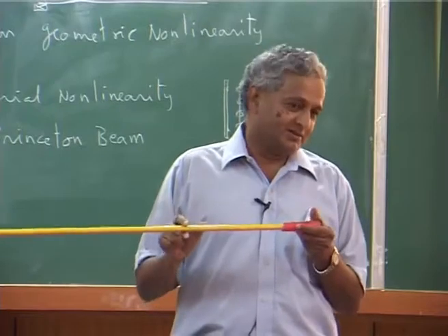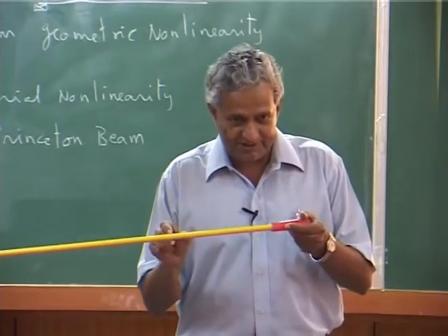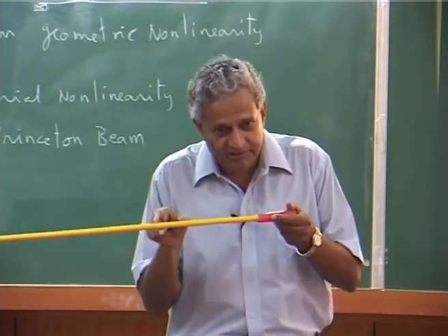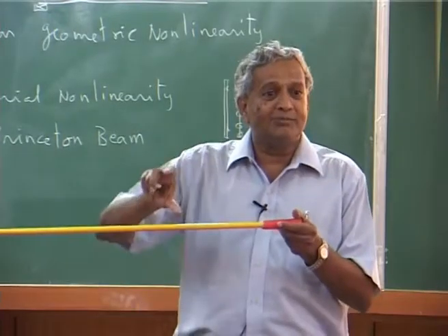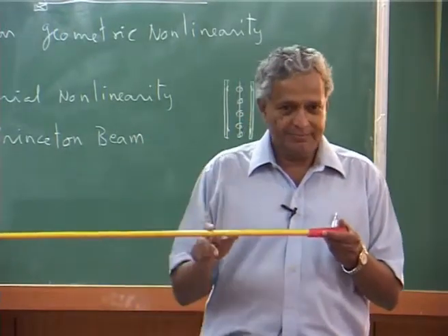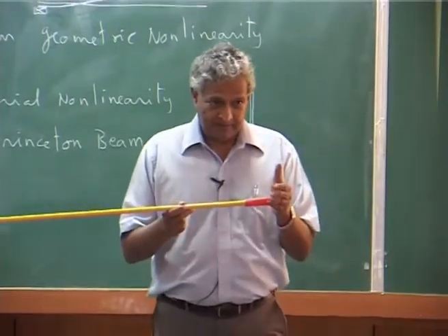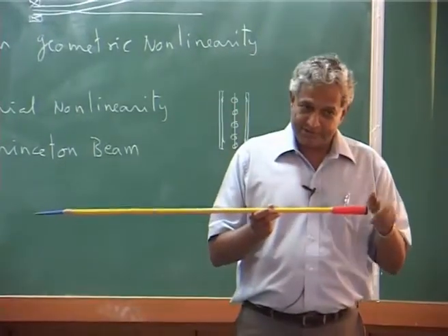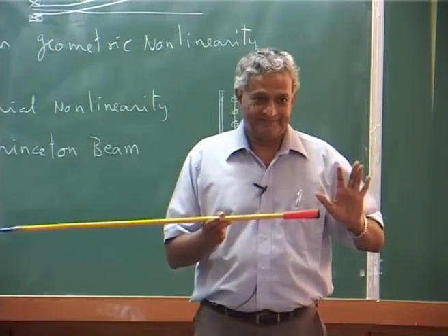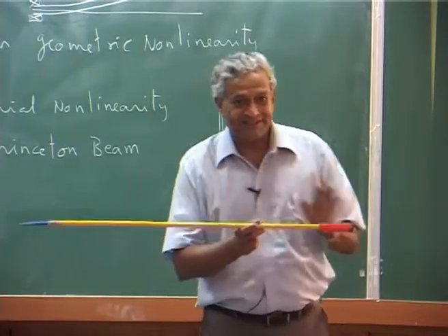It is a virtual hinge, not a physical hinge, but some point is soft, therefore it can flex about that point, okay. But the pitch bearing is inboard. Most of the hingeless blades have the pitch bearing inboard, you do not keep it outside, but you see that goes into construction.